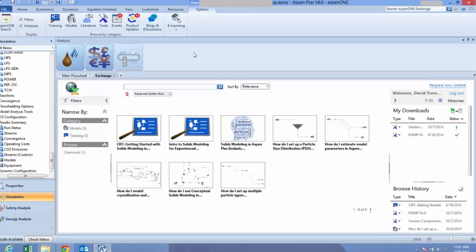There's a question about catalyst deactivation and the kinetics. Generally, with something like deactivation, these are long-term, time-dependent phenomenon. So typically in a model, you would fit that, just like you would fit, say, fouling in an exchanger, based on current plant conditions. So, if you are using a kinetics algorithm that considers a solid catalyst, you can tweak that through either the catalyst mass or through an activity factor.